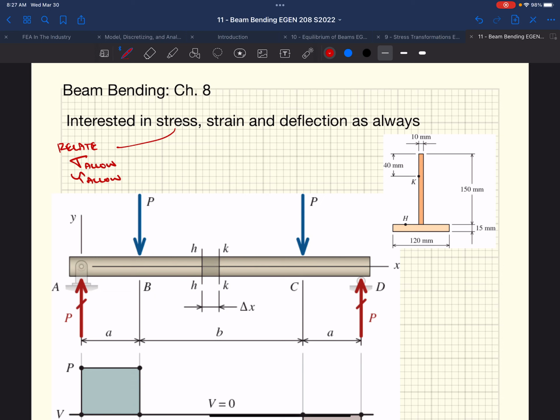We go back and based on the material that we select, or we can select a material based on the demands, right? Using a factor of safety to get our allowable stresses for that material, right? Based on the use of that element, right? Our ability to predict what the behavior is actually going to be.